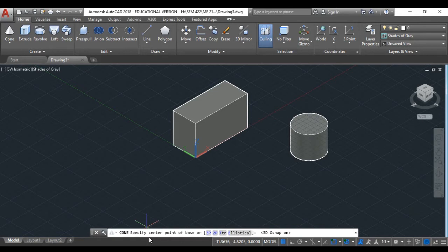Remember, guys, the reason that I take you to the object snap is because I decided this time to put the cone on the top of the box, right? So if the program asks you to locate the center, then I decided to make this one exactly at the mid location of that face. Then I have to go with which choice, guys, out of these choices? Center of the face. You got it? Did you see this little blue circle, guys? Maybe the colors are close, but still I can see it.